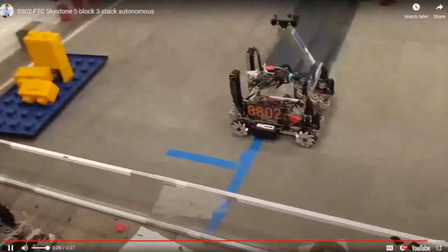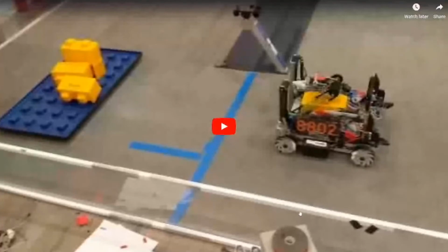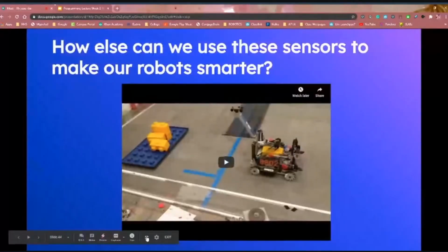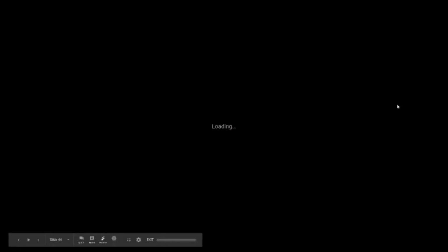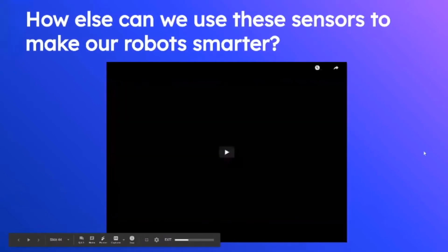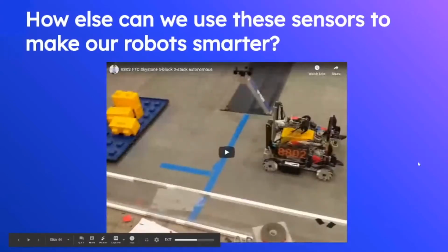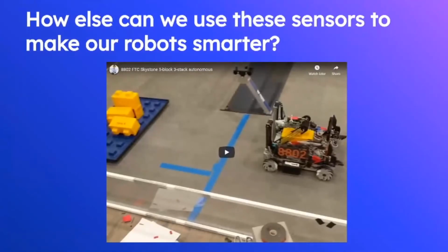I'm only watching it. But yeah, that's an example autonomous that uses different sensors. They definitely use encoders, to tell an exact distance that these motors will move, but it will also use what's called PID controllers, which is some calculus thing to be able to tell the robot to optimize its movements basically. So you notice that it doesn't just move forward and then back and then turn left 90 degrees. It moves super smoothly because that PID controller is able to calculate the exact electrical pulses that we need to send to our motors and everything.